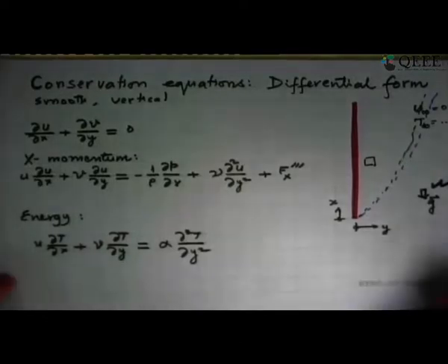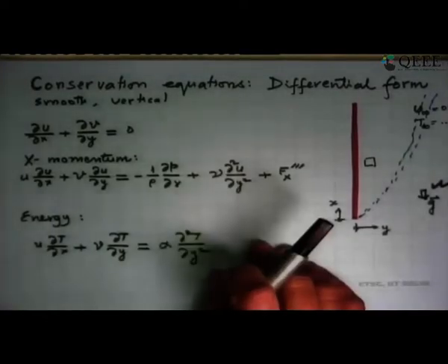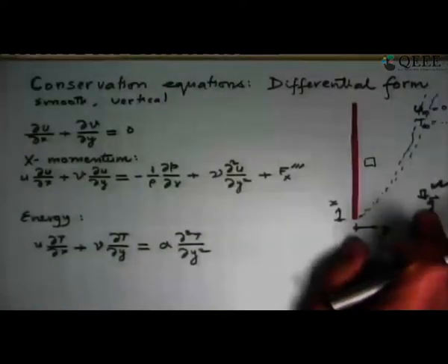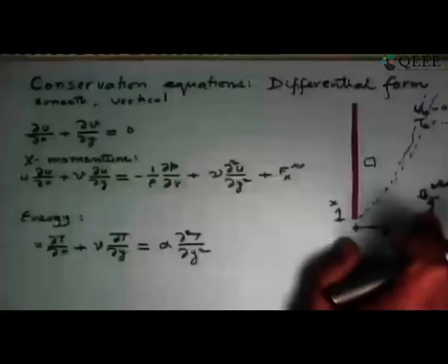I will leave it to you to think about what will happen inside the International Space Station. g is almost zero. It's a microgravity environment. And if you have a hot plate or something that is hot, how will it cool? And this is an important thing, because if you see pictures of that, they have a lot of electronics there, they do a lot of experiments, and especially if you have electronics there, like you have seen here, whether it's your UPS or things like that, it will have a heat sink. That heat sink is sitting in still air, so natural convection is cooling it.